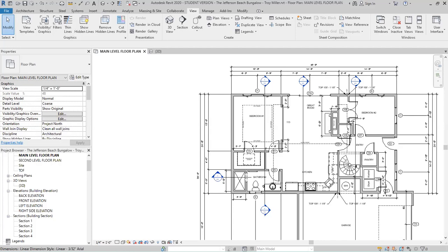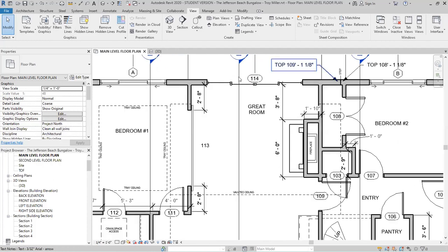these interior elevation callouts. So we're going to start with the one here in the great room, and in this case we're going to stay in view, and then you can see right here we have elevation. I'm going to drop down that little drop down. We have a framing elevation, and we have just a regular elevation.